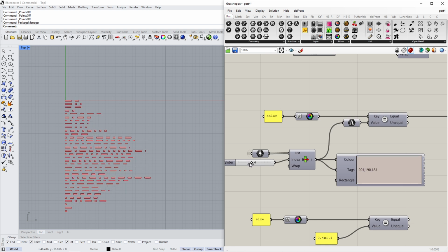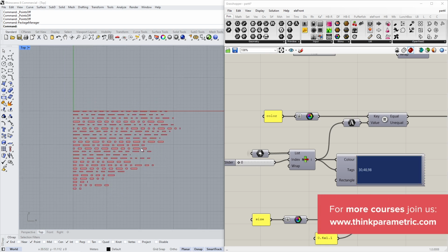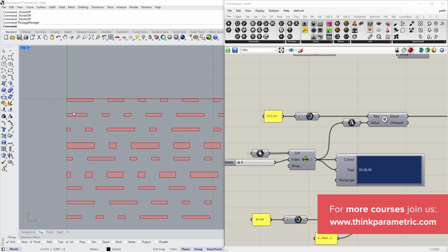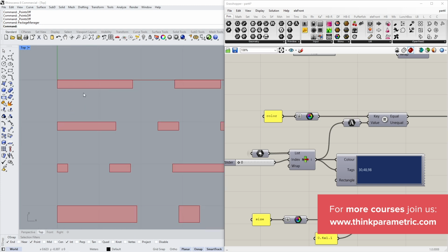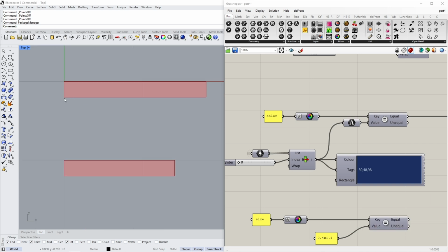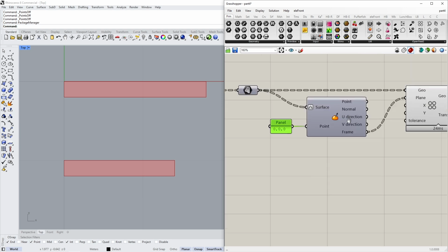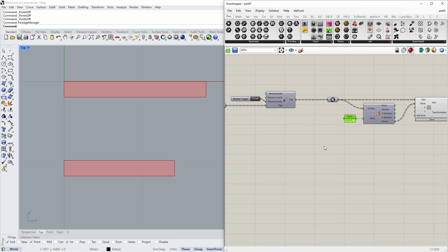and we get all those per color, we get them nicely laid out per row. But that's not all we can do. We can even include per tile their key value pairs. I think that's also very helpful to have per tile knowing exactly, hey, it's this size, it's located in this row and in this column. So you know the location in the facade where it's located, plus their size and their color and their ID tag even. Let's see if we can construct that too.